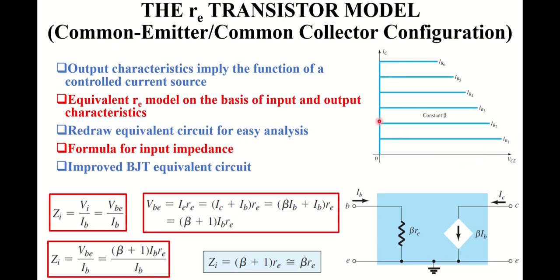By using this graph, we can include the non-ideal behavior and can achieve an even closer characteristic model of a BJT for AC analysis. Right now, we have considered that the value of current is constant due to constant value of beta, but actually these curves are not constant. They have some slopes associated with them, as we will discuss on the coming slide.